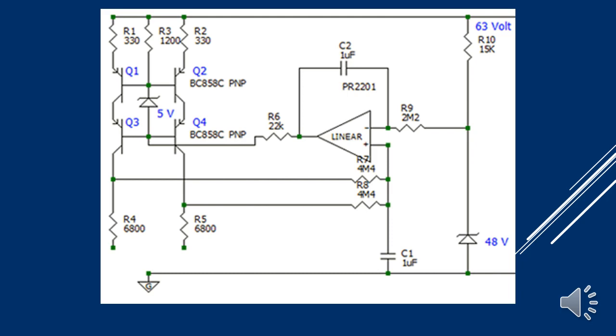This schematic works very well. You see here the reference voltage of 48. This op-amp will DC servo the current source. It gives that much current that 48 volts will be at the output, and then every microphone gets the current it used to get.